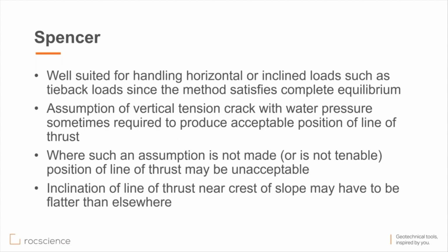It is very suitable for problems which have horizontal forces, like seismic or pseudostatic seismic analysis, or when you have support in a slope. But again, you might have to use a tension crack to deal with some of the problems. Otherwise, you will not get acceptable positions of the line of thrust.